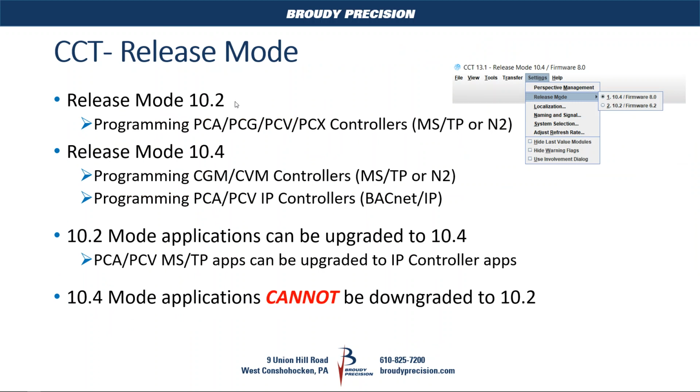As I mentioned, in the 10.2 mode, you can do the FX PC series controllers, MSTP or N2, whereas the 10.4 mode is used specifically for the F4 series, the CGM, CVM controllers, as well as the PCA, PCV IP-based controllers, the BACnet IP controllers.